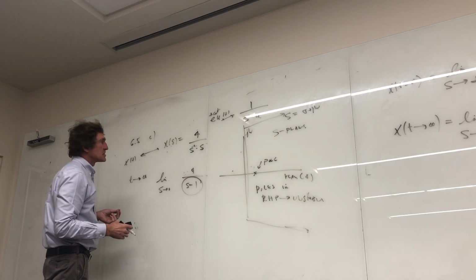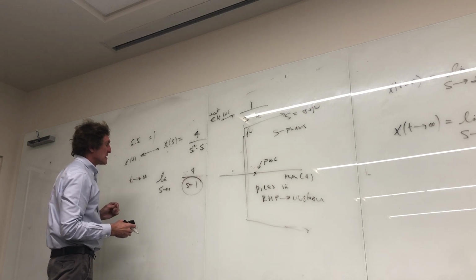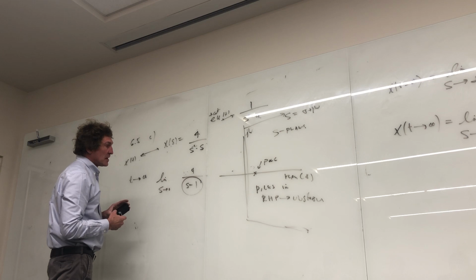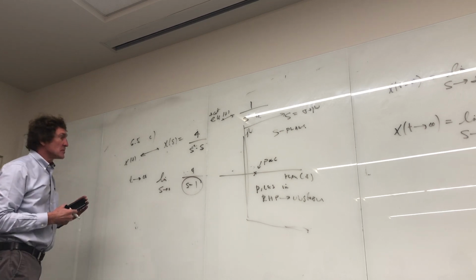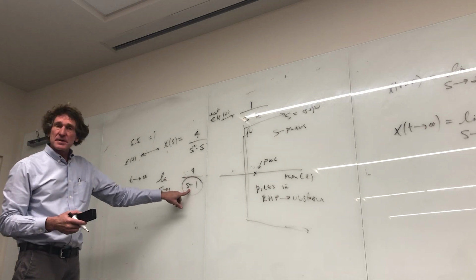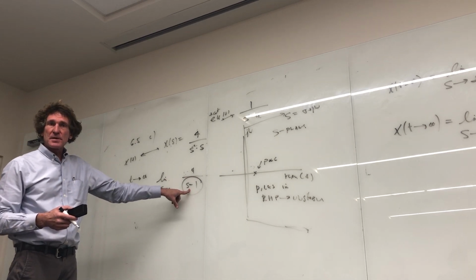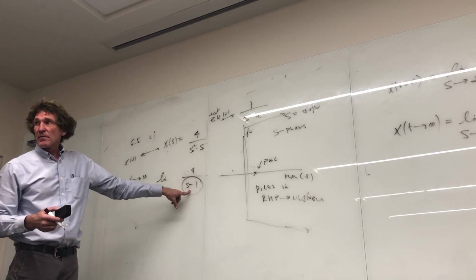they want the value as t goes to infinity of this. So if I multiply by s, I get this, and if s goes to 0, I get minus 1/4. And that's one of those that doesn't seem to show up. That doesn't seem to expose the property, but the pole does. Is that what they say? They say they look at the pole, or they do it? I think they said they look at the pole. But that's the way you tell, all right?